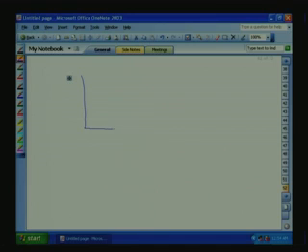Okay. Now, what do we want? We want to find out the instantaneous position of the rotor flux. So, if you know the instantaneous position of the rotor flux, let us go to the next page. This is your alpha, beta. Suppose we have placed the relative position of the voltage and current. In a similar way we can position the rotor flux psi r also. Let psi r make an angle rho.